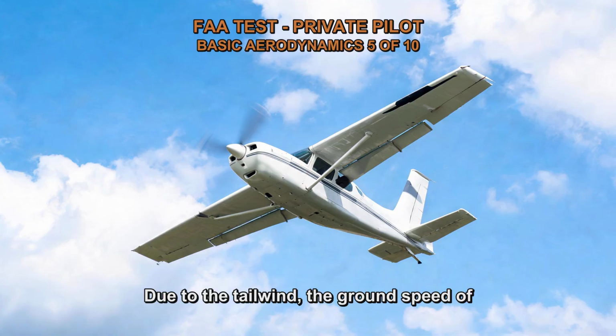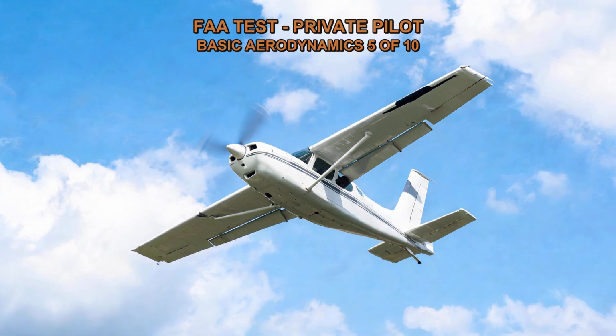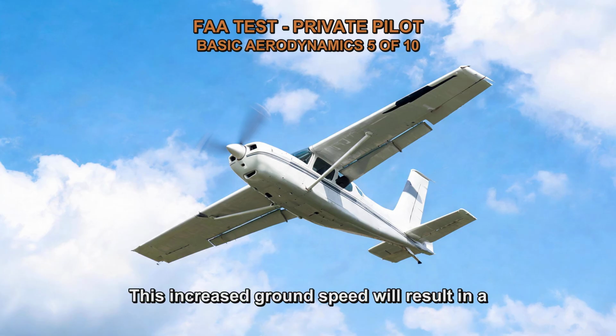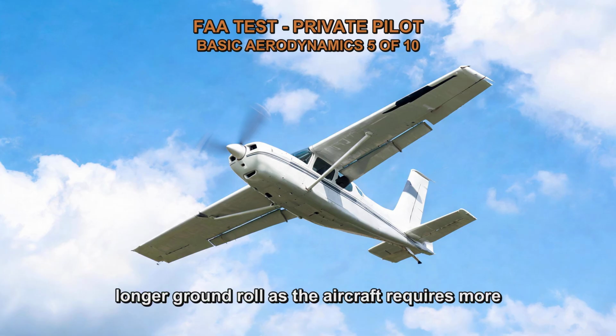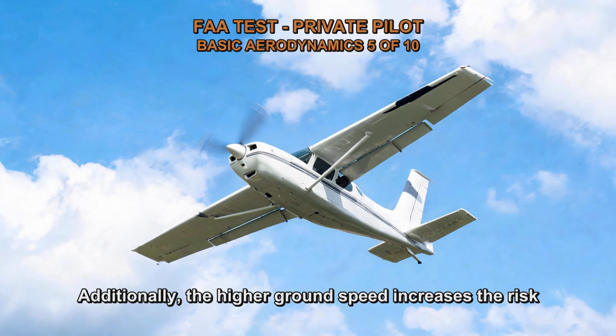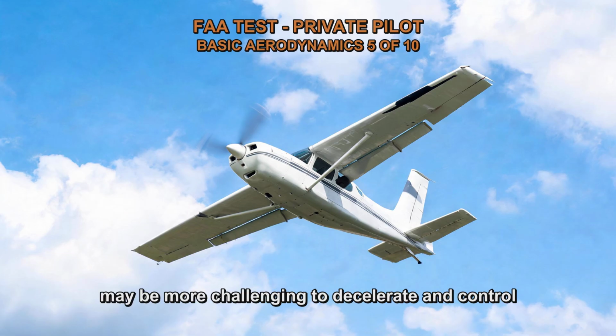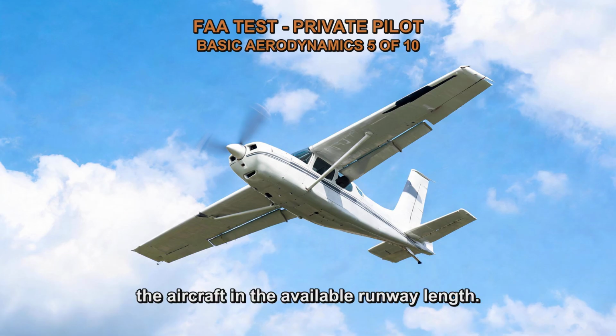Due to the tailwind, the ground speed of the aircraft will be higher than its indicated airspeed. This increased ground speed will result in a longer ground roll as the aircraft requires more distance to come to a stop. Additionally, the higher ground speed increases the risk of overshooting the desired touchdown point, as it may be more challenging to decelerate and control the aircraft in the available runway length.